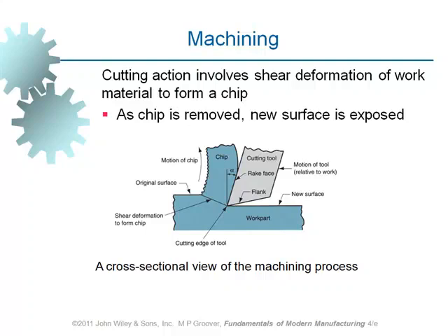And as we can see, the chip which is being removed is in contact with the top face of the cutter. As a consequence, there is a high frictional force being applied onto the top face of the cutting tool. And the material of the cutting tool has got to be resistant against wear and friction. Of course, it can last to some time depending on the magnitude of the applied friction and also the quality of the work material.